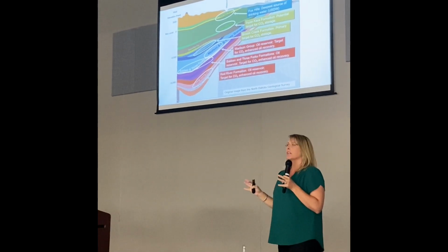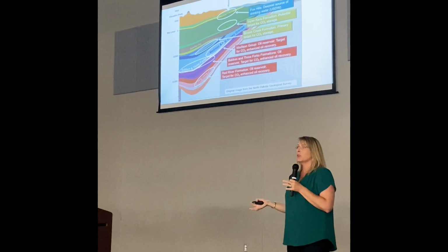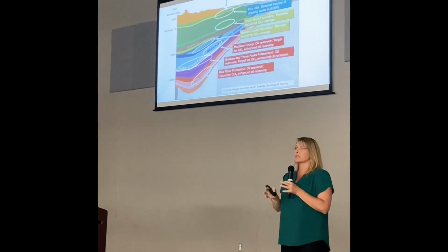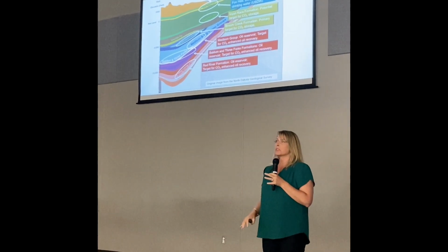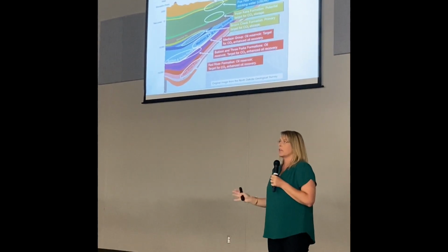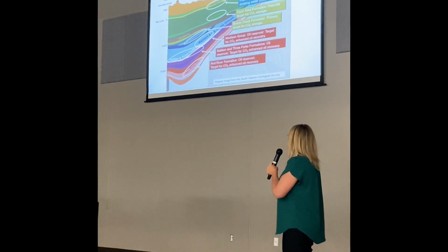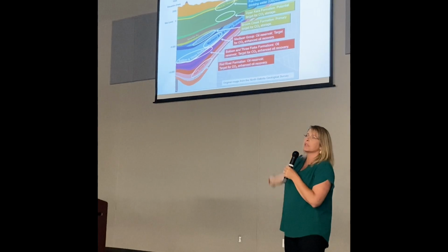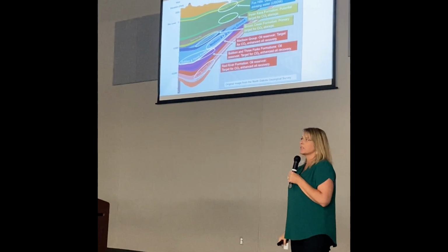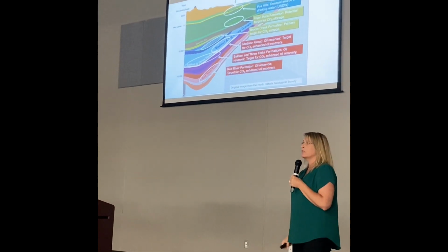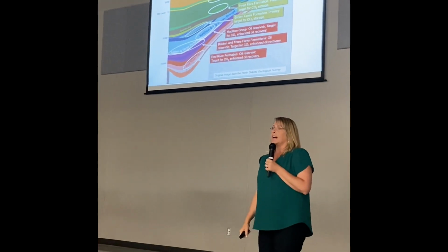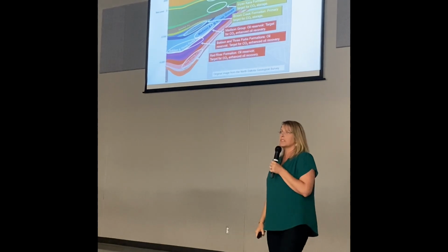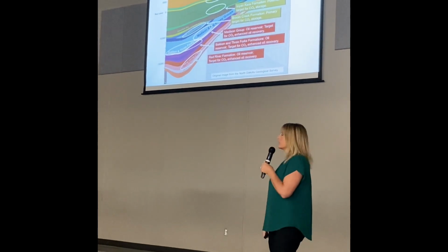And they are very careful whether you're drilling an oil and gas well or a CO2 storage well, very careful to put extra layers of protection in place through those zones to ensure that you're not going to contaminate any sources of drinking water. Potential CO2 storage targets, we have the Inyan Kara Formation. Many of you may know that as the Dakota sandstone. That's the number one target right now for saltwater disposal. The Broom Creek, that one's the one that's been most heavily targeted for CO2 storage.